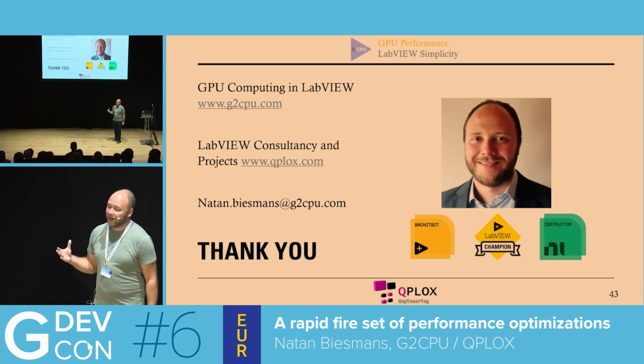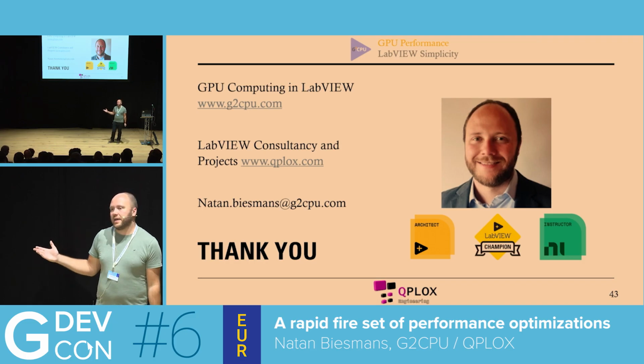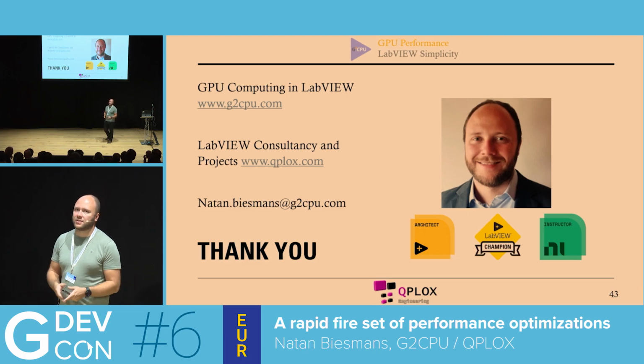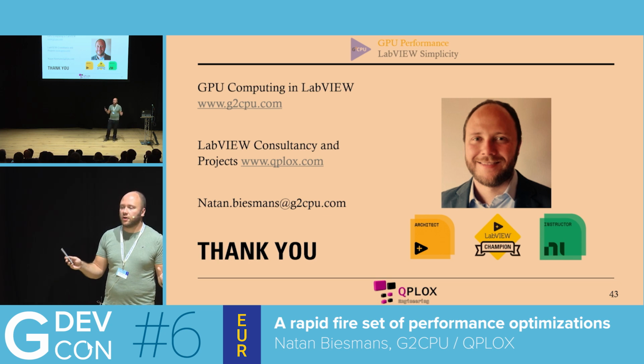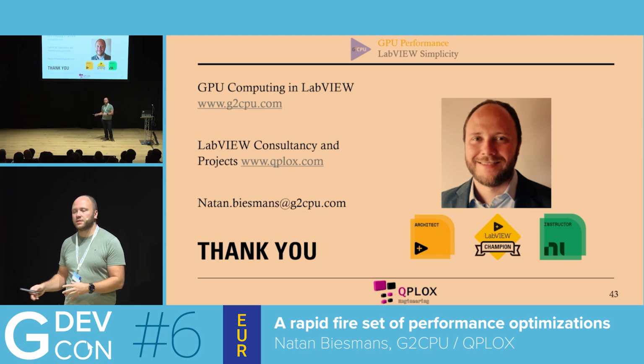First of all, I haven't seen any documentation on it. I might be wrong, but personally I haven't seen anything. But I found that the timed loop does get me a long way. One of the ways that I implement it is I use the priority of the timed loop, but I also use the fact that high priority functions tend to get a lower index on the processor ID, while lower priority items get a higher index.